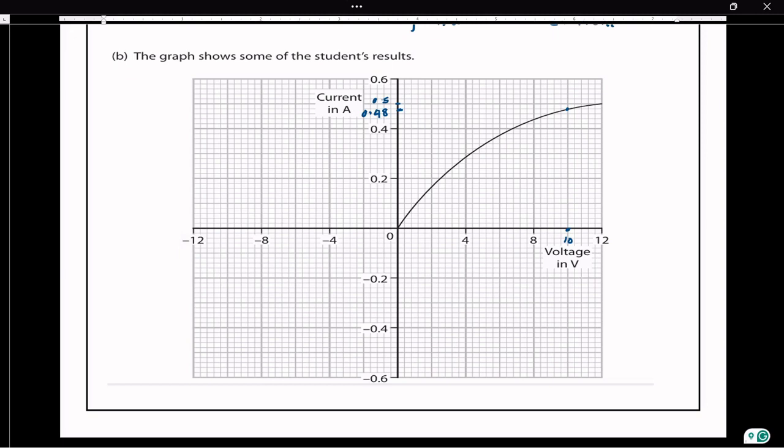So if you want to know that, 5 divisions corresponds to 0.1. Therefore, 1 division is 0.1 over 5. So each one is 0.02. So first one is 0.4, then 0.42, 0.46, 0.48 like that. So 0.48 is coming here. This is the number we are getting.